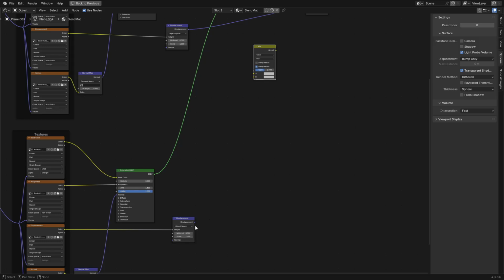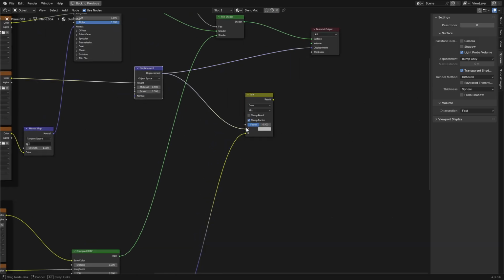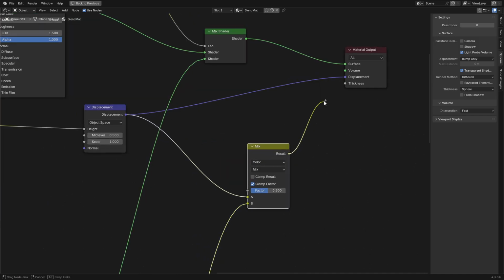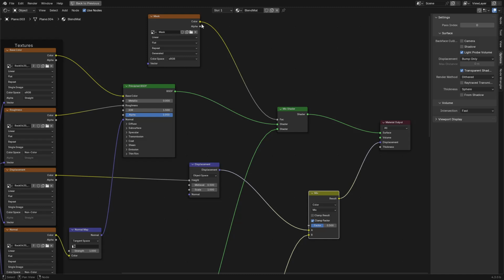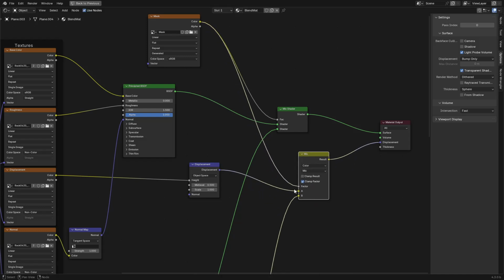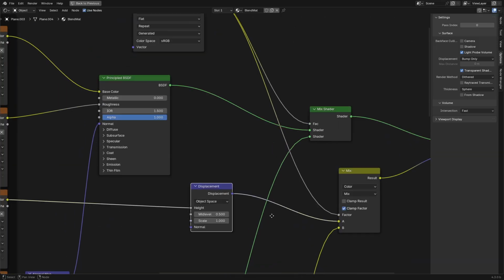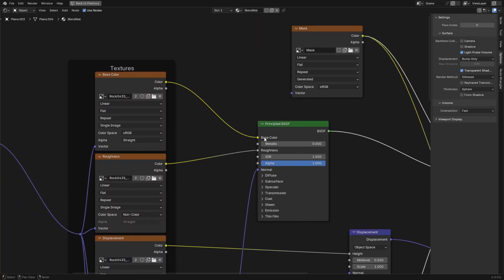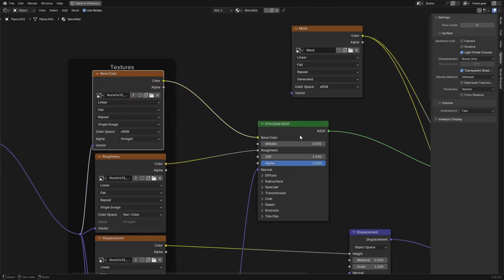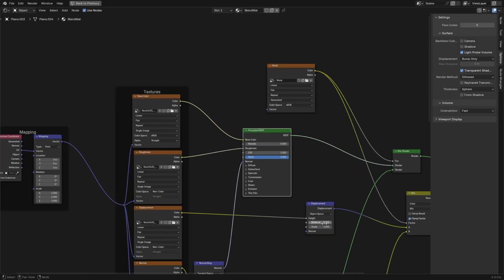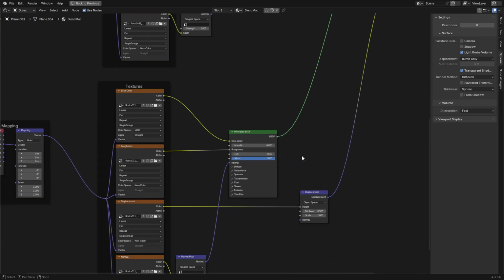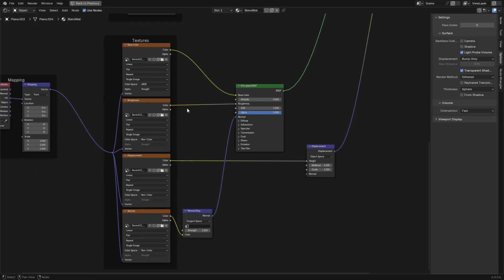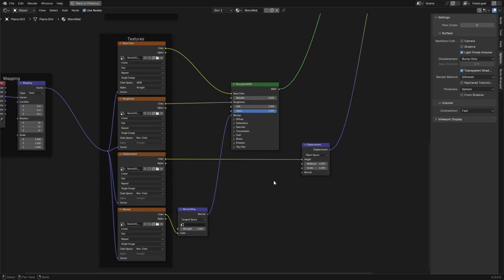All right. Here and here. And it's actually kind of simple because all we're going to do is plug that into there now. And we're going to use that same mask to drive our mix of these textures. Okay. So we're actually mixing the textures here as we're mixing the shaders here. It's more performant to mix the textures, generally speaking, but it's easier to do the shaders. So, I mean, that's a judgment call there. But you'll do a lot more work mixing all the shaders, obviously.